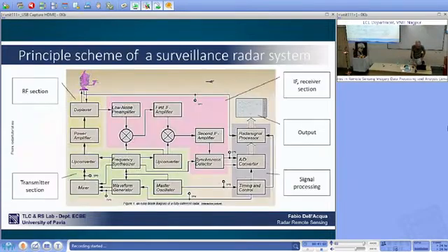The fact is that if you look at the typical configuration of a radar system, you will notice that there's a so-called master oscillator, whose signal is like a pacemaker, which memorizes the zero that we have set by generating the impulse. And this wave is used both for sending the impulse, but also for interpreting the returning wave. So when you send out your illuminating wave, you somehow keep track of the zero. And when the reflected wave comes in, you compare that reflected wave with the zero that you have memorized in time.